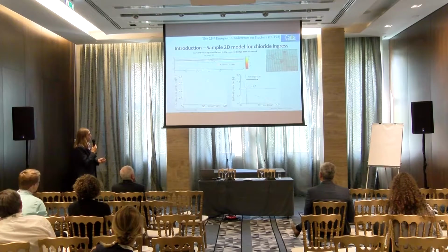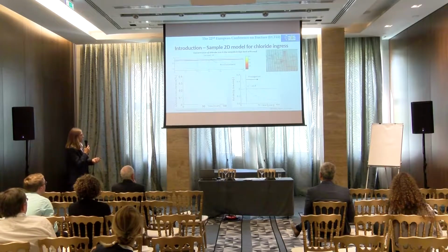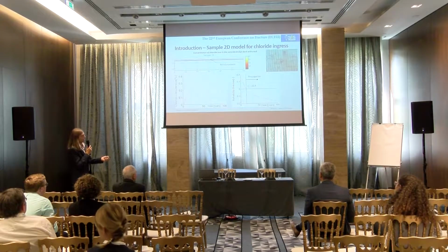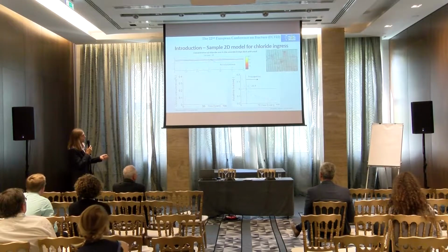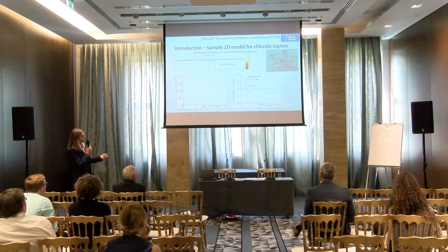And those two pictures are illustrative. The chlorides concentration increase at the reinforcement level for the time, and then here is the other way around. We compare when the chloride concentration is at the unacceptable level and the corrosion propagates.